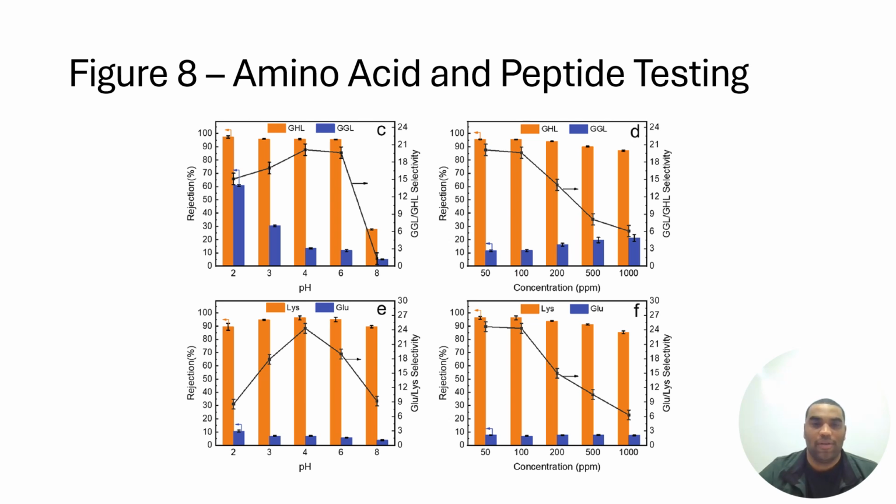The large problem for the NF membrane can also be seen in this data, that the selectivity for the desired molecules is relatively low, hovering between the low to mid-20s. While this is consistent with other types of membranes, both in research and commercially available, it is still the largest problem facing the NF membrane in being used as a widespread separation scheme for peptides and amino acids.